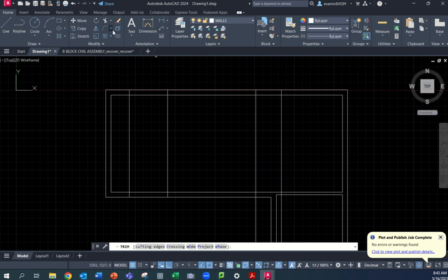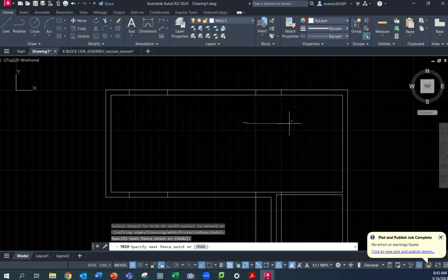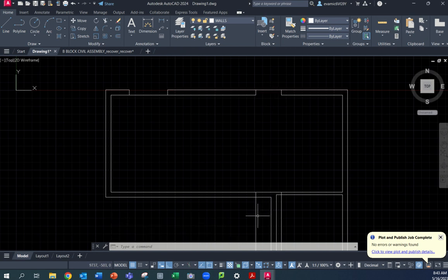We're quickly going to come and clean up here. I'm just going to drag my mouse across there and there. We can go and take out the outside corner of that window. So the outside edge, because we're going to need a windowsill in there. Obviously, we don't have any windows in this particular positioning. And the door here, we're just going to remove the inside edge. Remember, an external door will always have an external line for the little lip or step into the building. All right, let me delete these little lines down here.